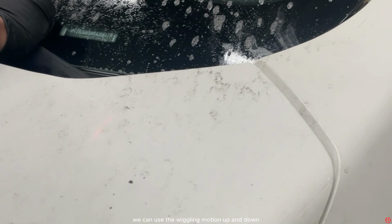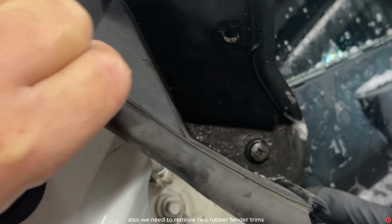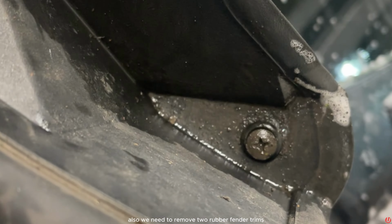Before removing the cowl panel, we will have to remove the 5 push pins that run along the cowl panel using a clips removal tool, also known as a trim removal tool. Also, we need to remove 2 rubber fender trims on the driver's side and passenger side. These rubber trims sit on top of the cowl panel. Also, we will have to remove 2 push pins on the edge of the cowl panel on each side of the vehicle.